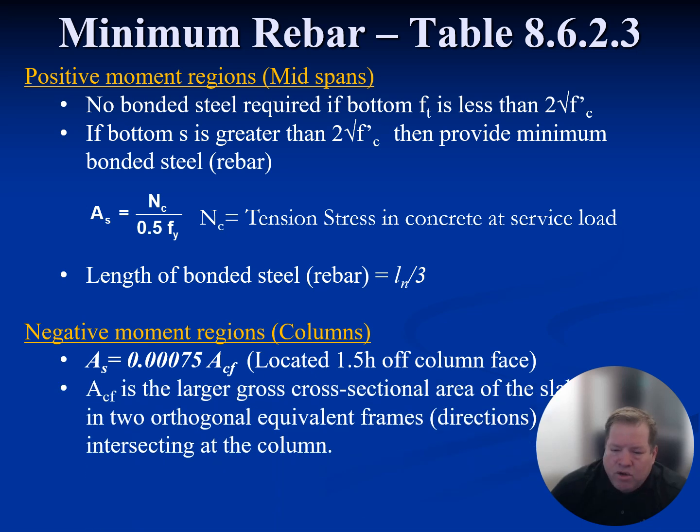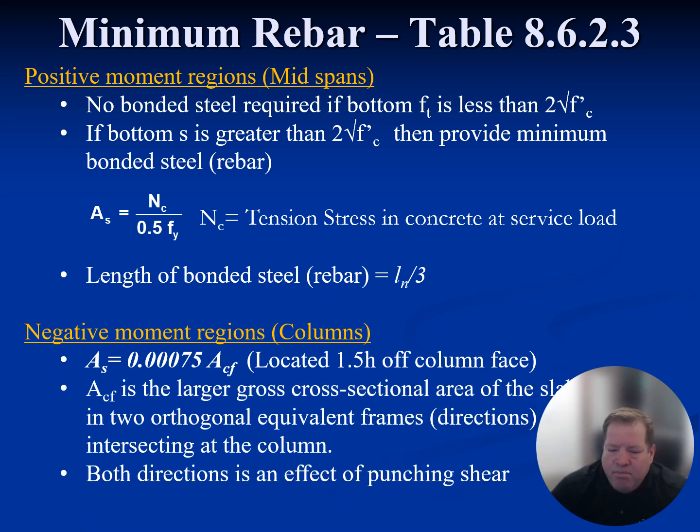The short answer is this is effectively meant for punching shear, to activate the tension strut of the punching shear resistance. I'll cover this in a little bit, but punching shear is our Achilles heel, and these two-way flat plates, like shear is for anything else in concrete. Flexurally, I think we have unbelievable amounts of reserve strength, catenary action, spider webbing, whatever you want to call it. But punching shear is immediate. It's not really ductile, and once it starts sliding down, that's pretty much it.